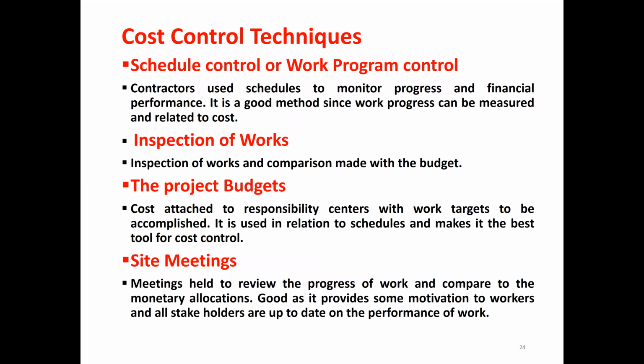Now again, we can adopt a number of cost control techniques. One is schedule control or work program control. Contractors use schedule to monitor progress and financial performance. It is a good method since work progress can be measured and related to cost. So these are different techniques that we can use in controlling the cost. So the first one is schedule control or work program control.